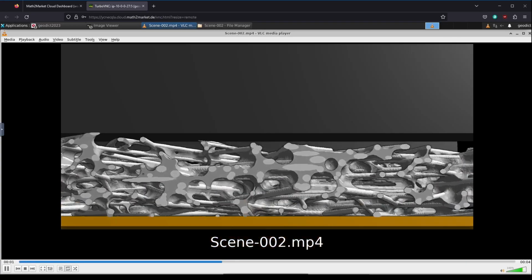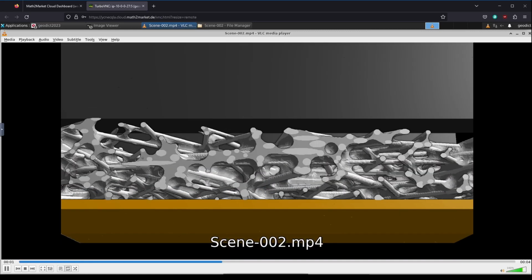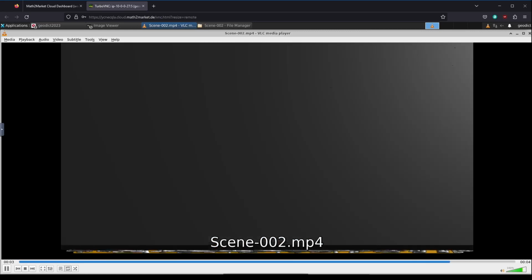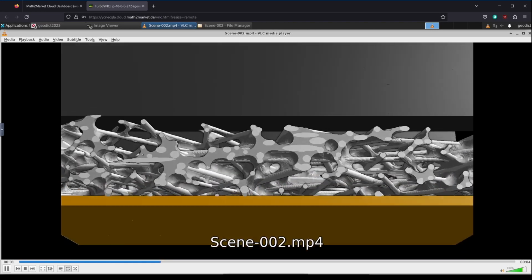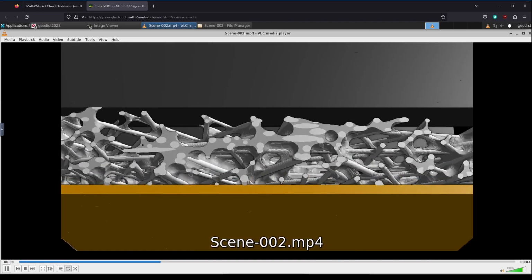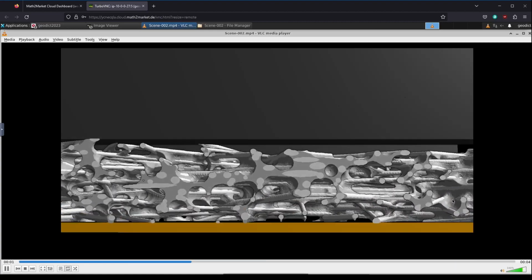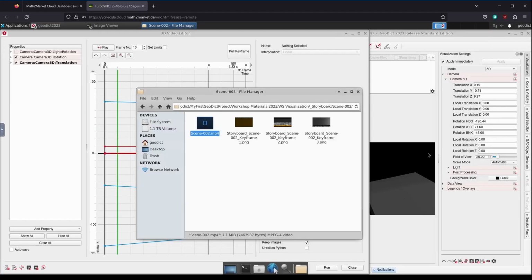We're dealing with a relatively simple animation in this scene. Our structure will be rotating 180 degrees around the x-axis. The light source will be in a fixed position for this scene. Additionally, we'll animate the color of material ID 3 and 4, the MPL and the flow channel, at the beginning and end of the video, and set it to black to create a seamless transition from the first scene and to the third scene. So let's get started.